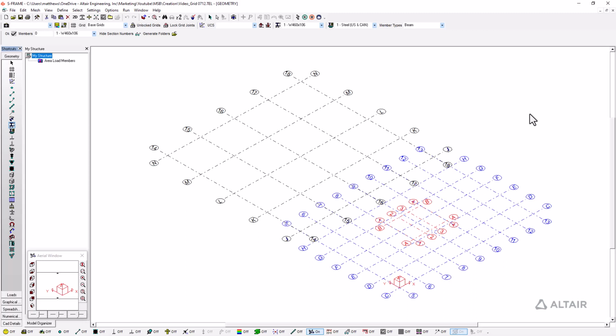In this example we're working on the creation of a building that has a multi-story tower with the core in the center. The tower and core are reinforced concrete, and it will be adjacent to a podium structure comprised of a composite steel structure. We're now going to look at how we can use the Multistory Builder functionality to create this type of geometry by laying out our floor plans and creating vertical stacks of stories that all relate to one another and can be easily adjusted.